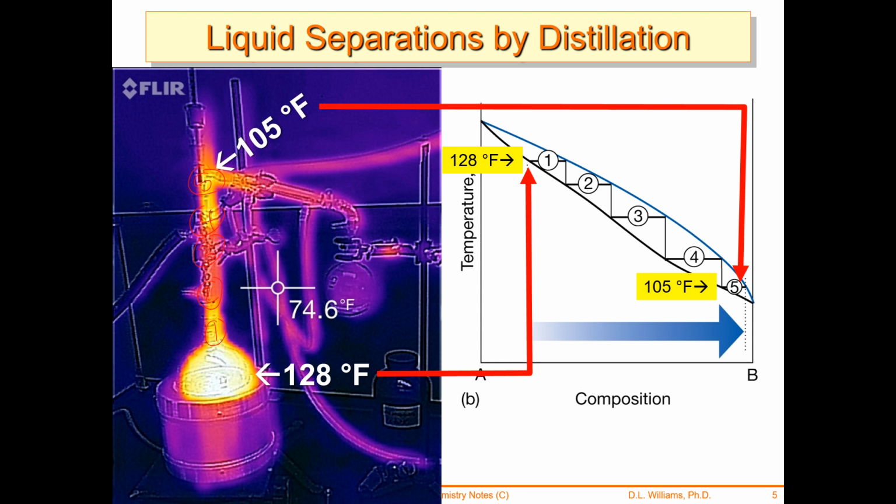It takes longer to distill the smaller the spaces, naturally, because you've got to get your materials up there. So our steel chain is cheap and it doesn't clog the column too much. Glass beads would clog the column quite a bit. You could get the same separation in a shorter column with glass beads, just because it takes longer for the vapors to get through the glass beads.